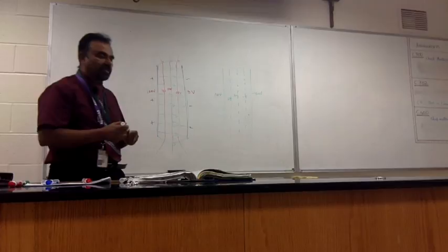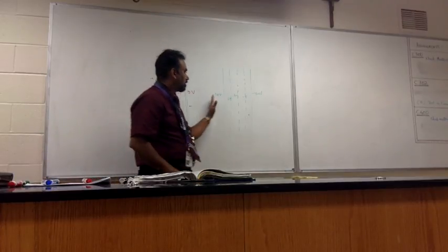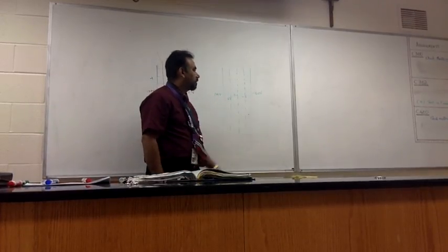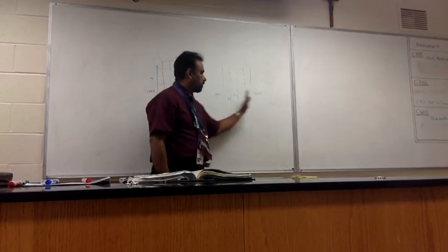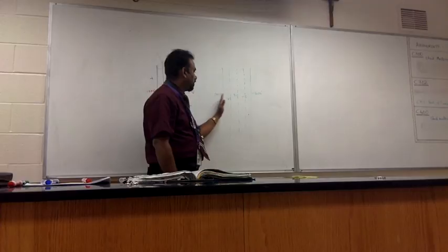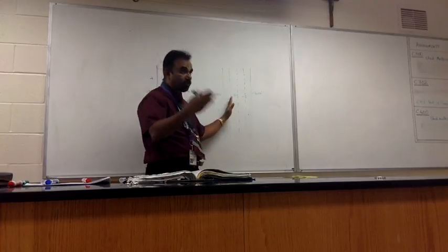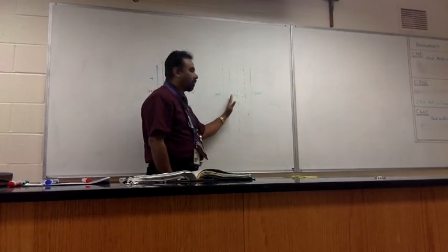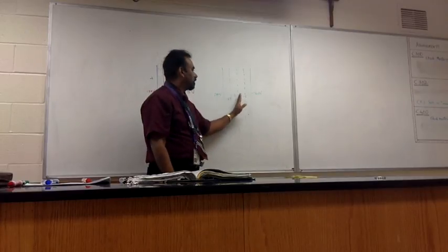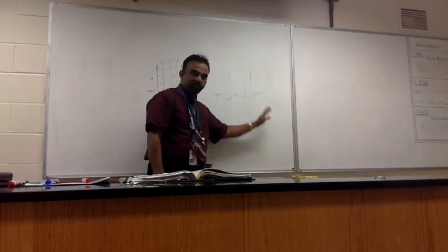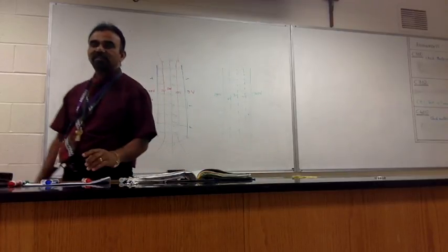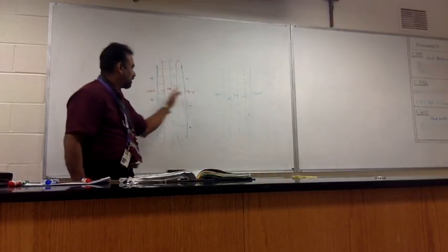So you can see the way it is dropping is very proportional. From here to here the drop is 140. So from here to the middle it should be 70. From here to here it should be a drop of 35. From 100, a drop of 35 brings you to 65. Drop of 35 to 30. Drop of 35 again. Okay? So it is not necessary that you always have 0 on this side and 100 on this side.